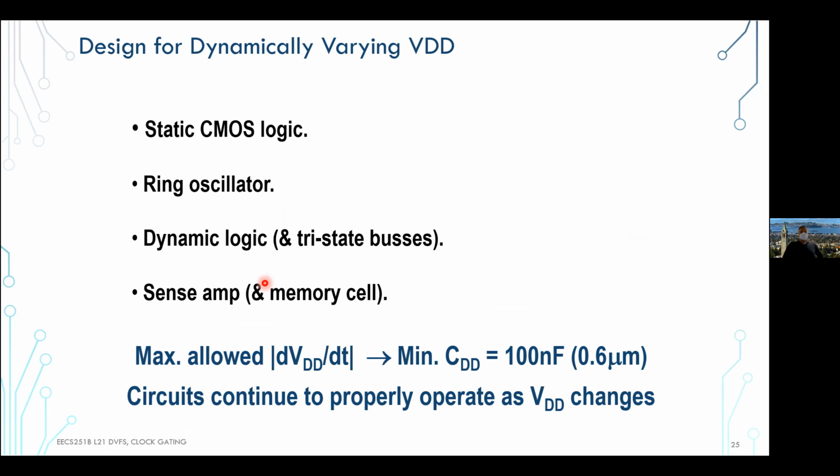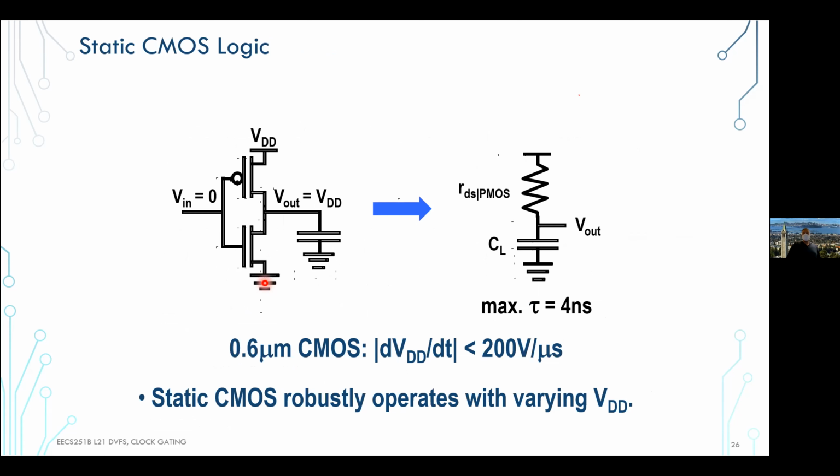Okay, so some more circuit considerations here, right? So how do you deal with some of these things? Well, we already talked about it. These are like some of the laughable numbers, like 0.6 micron. But the key thing here is that CMOS scales reasonably well. It's established that it has this nice voltage frequency or delay voltage curve that you can ride up to a certain point. One thing you need to pay attention to is as you're increasing the supply toward a certain point,